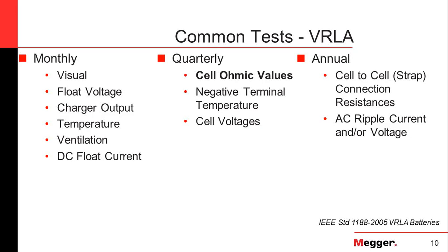But you'll also notice that the grounds, the unintentional grounds, are gone. However, it is stated as part of the precautions within the standard that you are to verify the voltage to ground before you begin any work. So if you follow the standard, you're still going to notice if there are any unintentional grounds by doing that test as well. Typically, these chargers are going to have some sort of ground fault indicator in them as well.